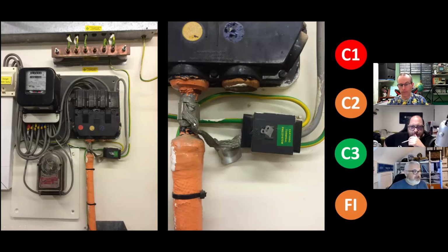PME system. That's interesting. So if we look on the grey cable coming out here, it goes up into the neutral, but we also have an earth clamp. Is this like a Frankenstein cutout or something? Or is this a common thing? It's a common thing. I was told by a jointer the reason why some of them leave them in is because, depending on where it is in the network, that is left in situ to ensure there is no potential difference between the sheath of the cable and the supply earthing system.